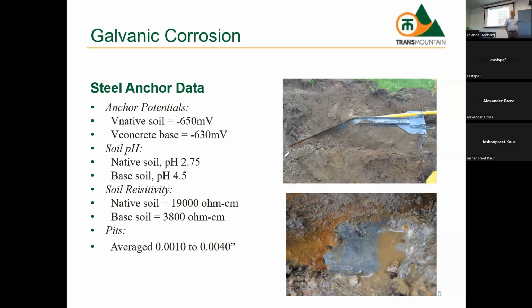I'm like, okay. You know what the issue is? Galvanic corrosion. The copper is the cathode. The steel is actually the anode. So the copper is being protected cathodically and galvanically by the steel. The steel is corroded to protect the copper. But in doing so, the support went away.